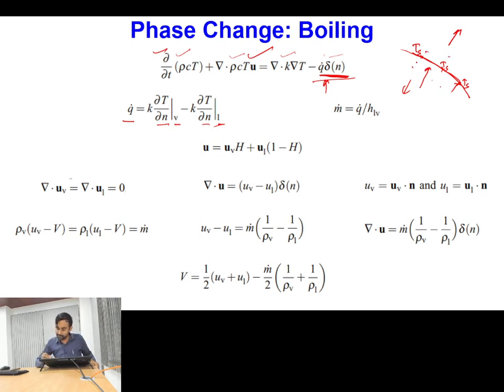Okay, now what you can do, you can draw a straight line near the interface, and this straight line is not too long, you will just be extending it to say 1 or 2 cells on each side. So once you calculate temperature, say this is one cell and this is the next cell, and at this cell center you know the value of temperature.